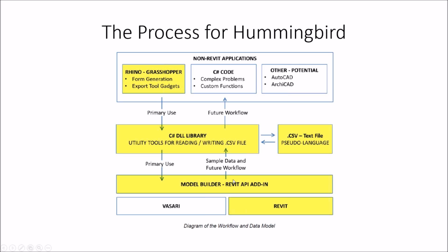The reason I like Hummingbird is because rather than just taking a mass object in Rhino and creating a mass object in Revit, which a lot of these tools do, you can use Hummingbird to actually push geometry from Rhino to Revit as systems. So you can push floors, you can push grids, you can push beams, you can push storefront. So it allows you to utilize the systems within Revit rather than just pushing a mass object from Rhino to Revit, creating another mass object in a sense.